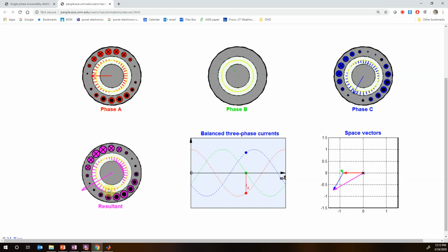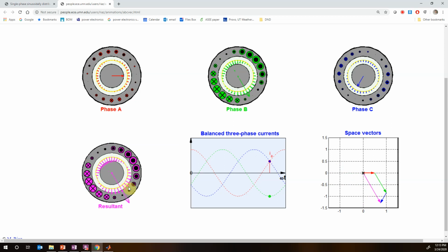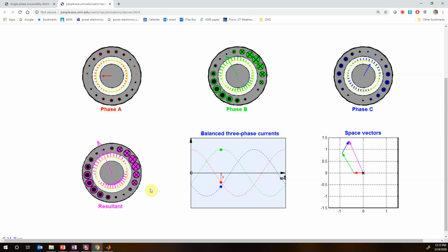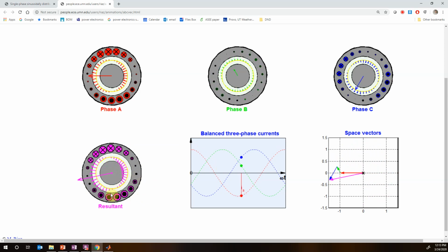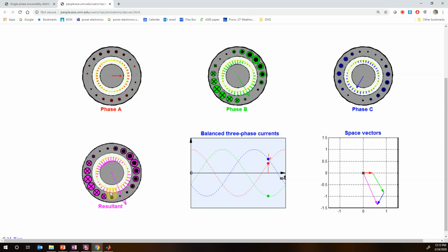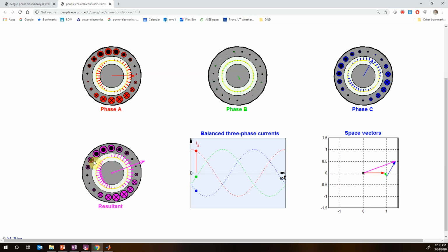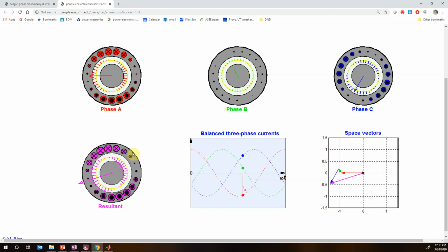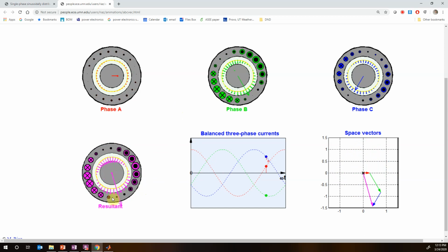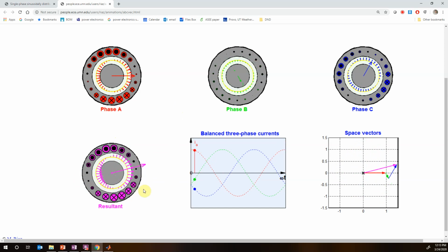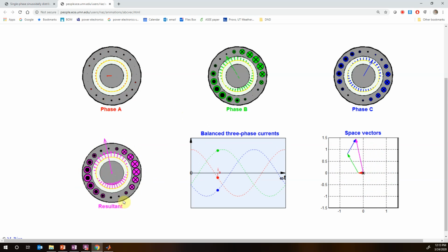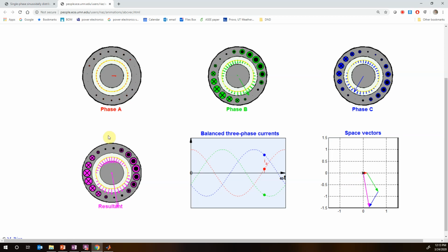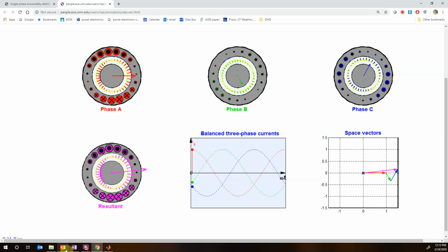And that's shown in this one right over here on the far left, that the magnetic flux is almost like it's just rotating around. So what we've created is a rotating magnet, right? The length of the magnet stays exactly the same, but we're rotating it using the phase of our voltage, not a physical change. So we get a spatially varying magnetic field that's all changed electrically. And that's the power of this three-phase power plus the sinusoidal windings.